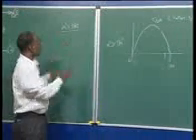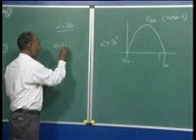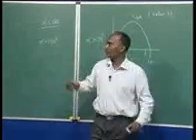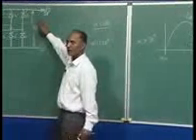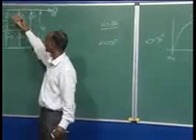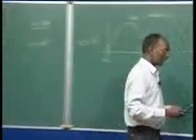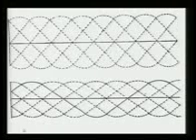So now if alpha is 150 degrees, we have to draw what will be the output voltage, and we will also find what the voltage across any of the valves will be on the same figure. Again, the top figure shows the line to line voltages, and the one below can be taken as the phase voltages.